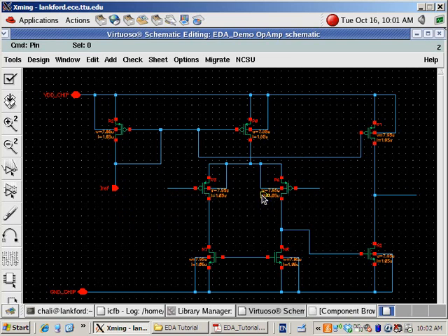And which side is the plus, input plus? Left or right? It's gonna be the right, because this is a two-stage amplifier, one inversion, two inversion, right? So, and I can use the right button of my mouse to rotate this pin so that it looks nice.